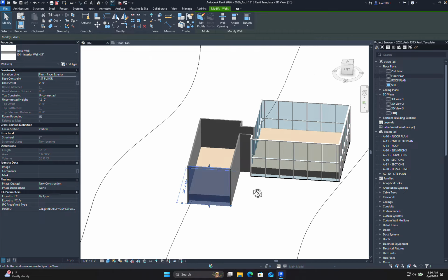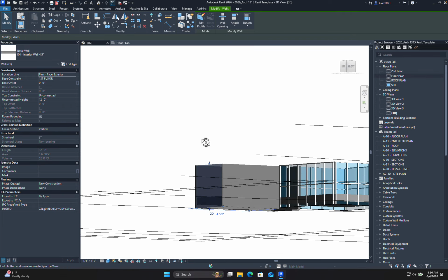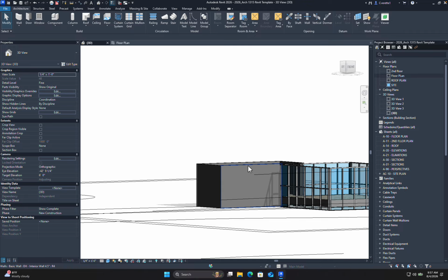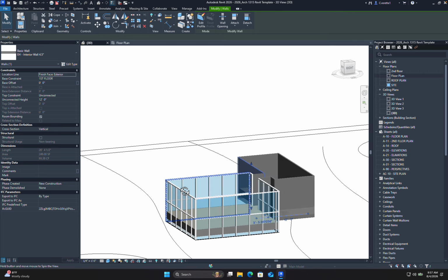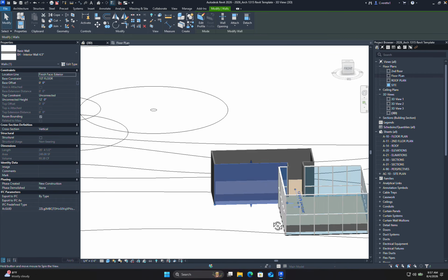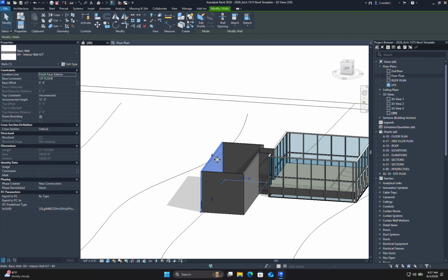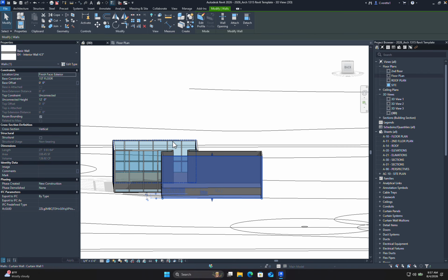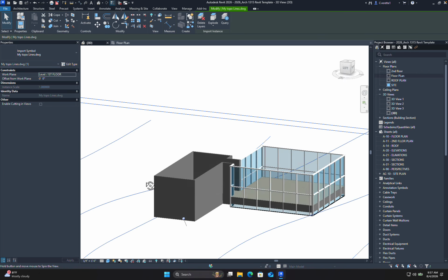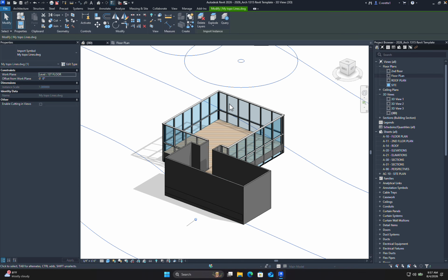But in our case, also another way Revit works is that clicking on something actually controls our center view. Just like in Rhino, how you can zoom extents to a certain object, Revit is automatically doing that when you click on an object. So if I click on this object, it automatically centers to that, both in view and rotation, right? So if I want to rotate around this wall, I can rotate around that wall. If I want to rotate around the entire surface, right, now it's center justified. So, you know, just some things to be called out. Another thing you may notice me using is this view box, and that's pretty nice.